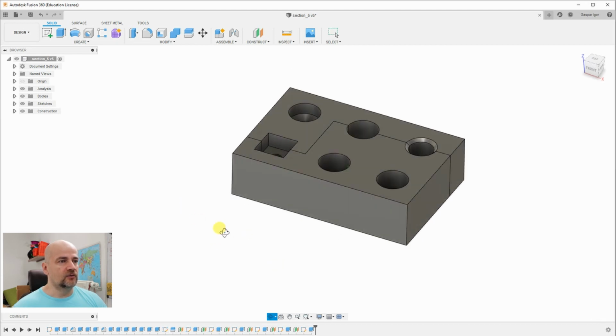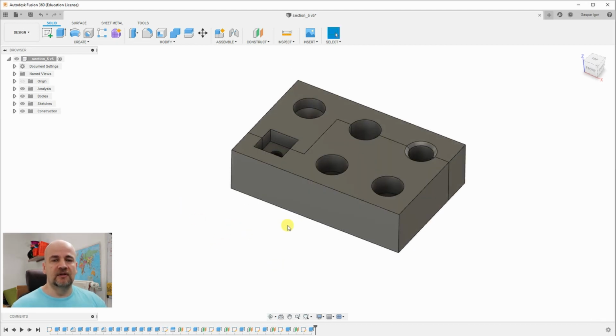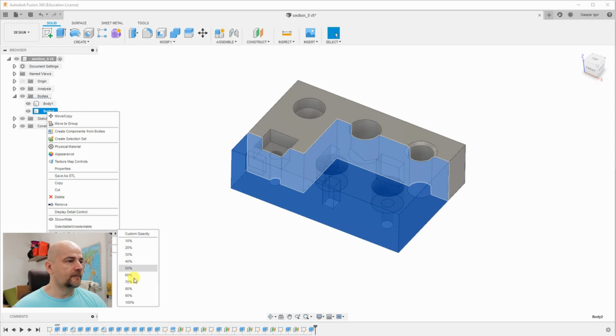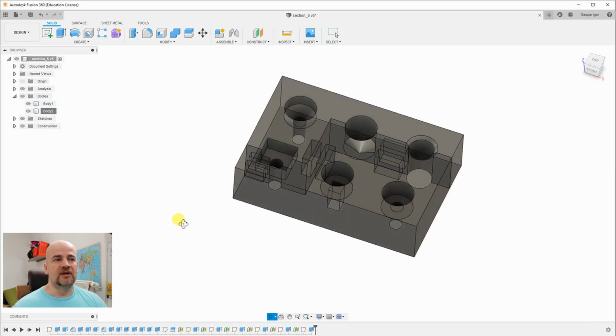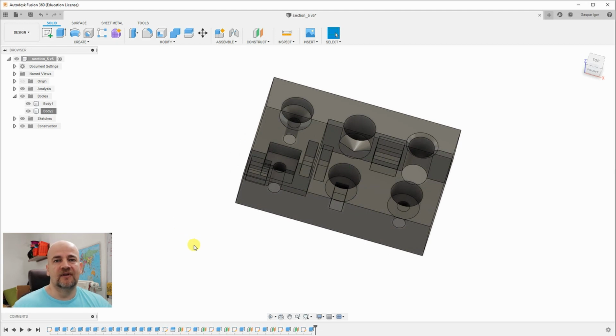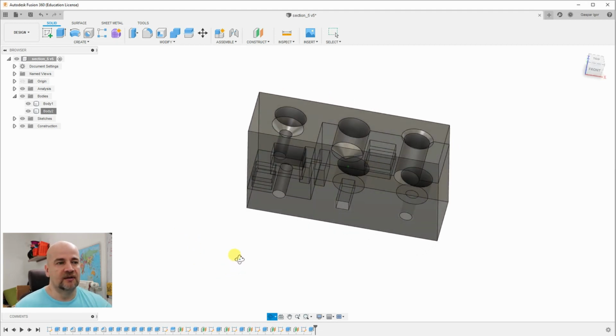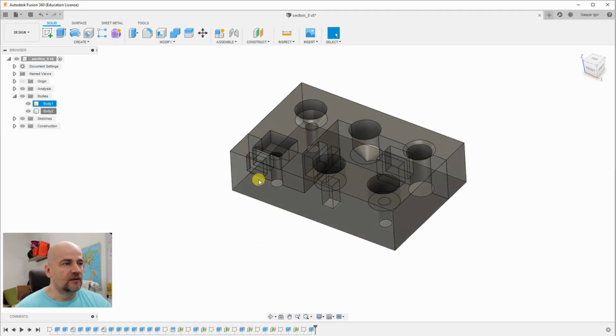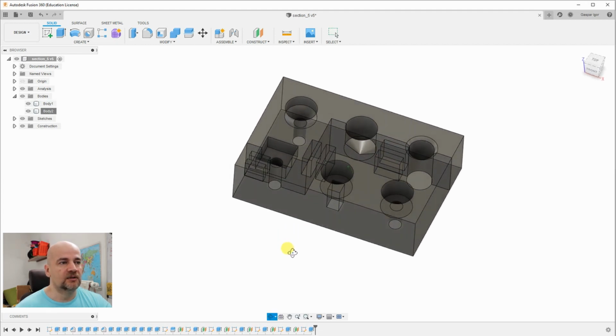And then the rest I had to do was add those holes, but that was explained in detail in the first object. I will only show you in transparency that those holes are there. I always measure the magnet and add 0.1 millimeter of clearance. I use different sizes of magnets because I use some waste magnets, some broken magnets, so I want to use them somewhere. As you can see here, 1, 2, 3 pairs of magnets will be added in this object.